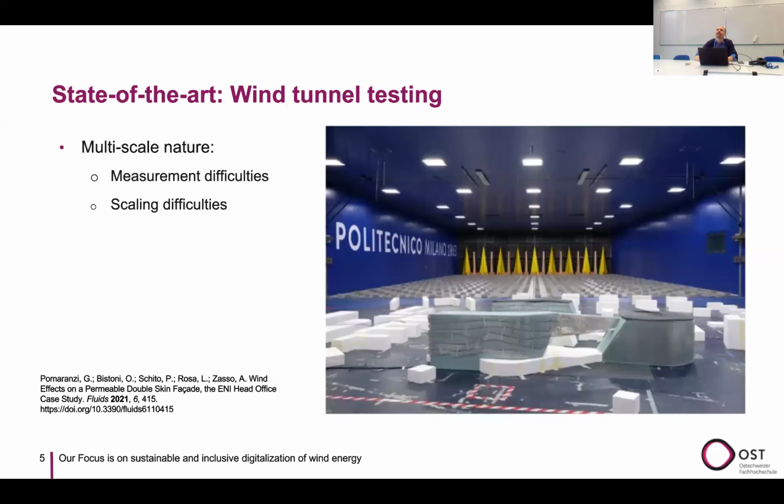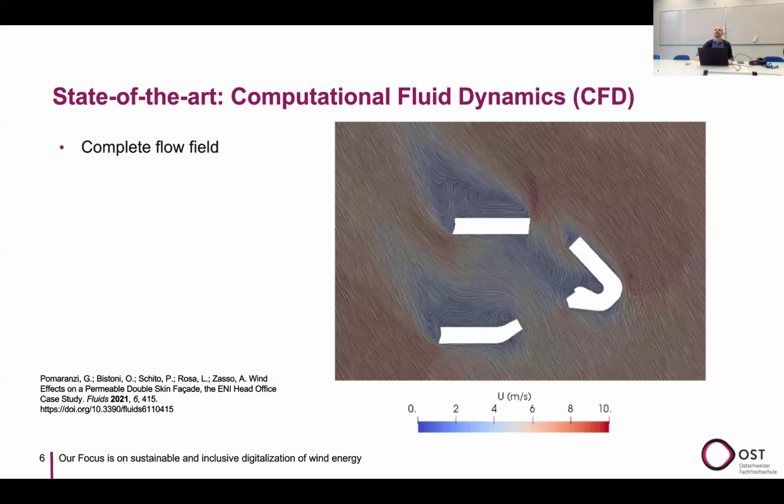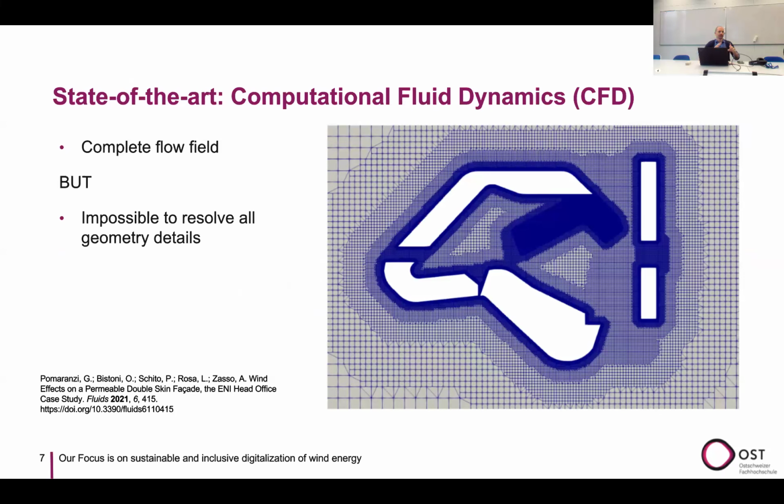I don't have a picture here that would be nice to show, but a building would be tiled into areas, and each area would have a pressure tap, and the reading from that pressure tap gets extrapolated to all that area. Usually it's just a pressure map, which would be dynamic, so it would have to be run with dynamic analysis.